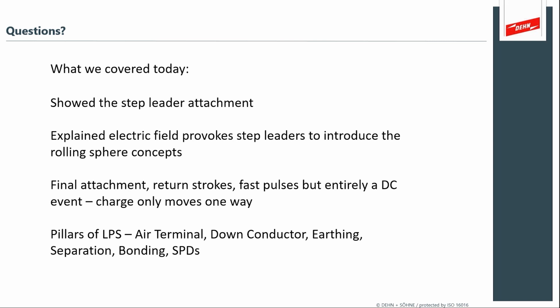I just want to say that you can take into consideration the distance that the lightning protection components are away from each other, and remember that every sphere has a penetration arc, so you can calculate what that depth of penetration of the rolling sphere would be between the air termination rods, and if that penetration is more than the height of your equipment on the roof, you know that the equipment is not within the zone of protection.